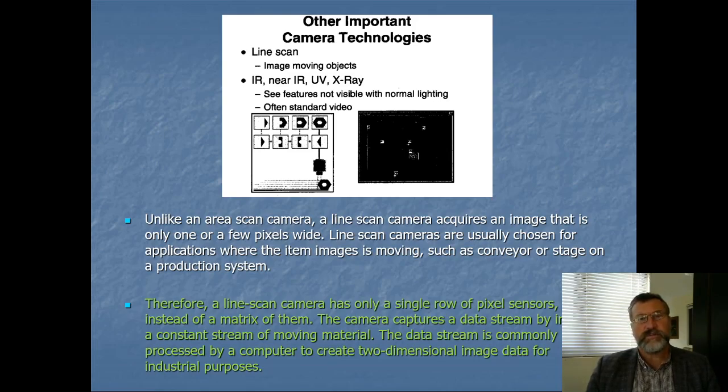I've been looking recently at some very high-speed document scanning capabilities. I bought these cameras, which are coming from Canada, and they're capable of 200,000 lines a second. Each line is up to 8,000 pixels long, so you can imagine you can get some pretty massive amounts of data coming off this technology. It works especially well if you're trying to image things that are continuously coming along a conveyor, and it works better than an area scan, because with area scan, you get distortions up towards the corners of the image. You get something called barrel distortion due to the way the lens works.